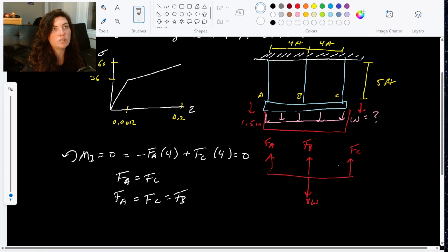These three forces are going to be equal because of their same displacement, modulus of elasticity, even their perfectly plastic region follows the same linearity if they're in the plastic region. Length, area, all of those things are contributing to these being the exact same.